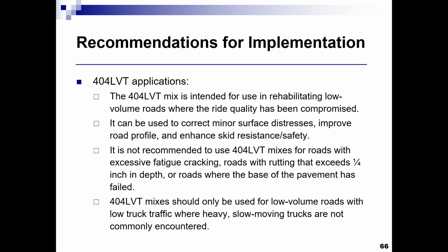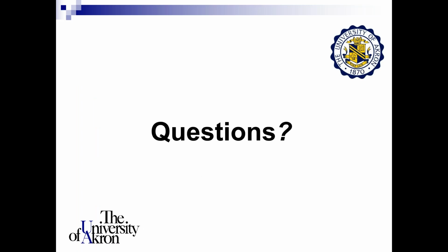I just want to remind everybody that this mix is intended for low volume roads. You cannot use it at a location where you have significant amount of cracking. You cannot use it at a location where you have significant rutting, and you have to use it at a location where you don't have too many heavy trucks. So you have to be very careful where you use this mix.